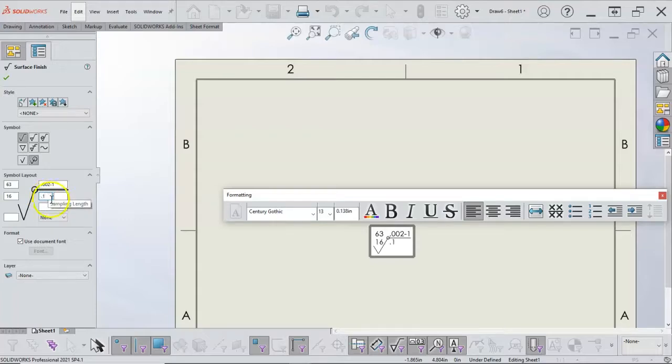build. So we did 0.1. I'm just going to reproduce what I had, 0.02, with a multiple direction callout. All right, so that's way more complicated than it needs to be. For most surfaces, I could probably get rid of all of those and just say I need a 32 finish on this surface. And if we even went to the all around, within that callout would give me a decent finish to work with.